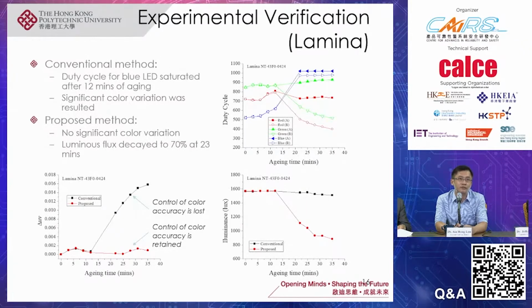So we actually make use of two different RGB LEDs made by two manufacturers. And then we age them, in an accelerated way, of course. That's why you notice that the aging time here is very short, but in fact, we have applied very high stress to those LED samples to cause them to deteriorate much quicker.